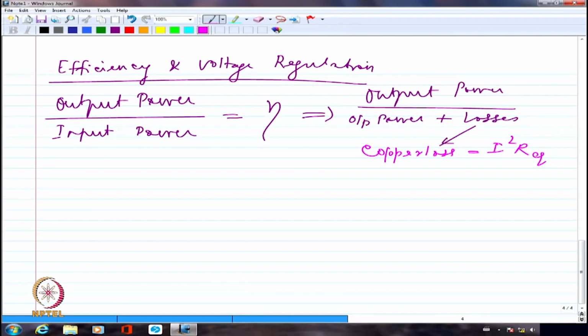If I connect 5.5 ohms in the 2.2 kVA transformer, it will be supplying rated power of 2.2 kVA. If I connect 10 ohms, then correspondingly I will have 11 amperes only instead of 20 amperes. So the current is a variable one depending upon what kind of load I have connected, right?